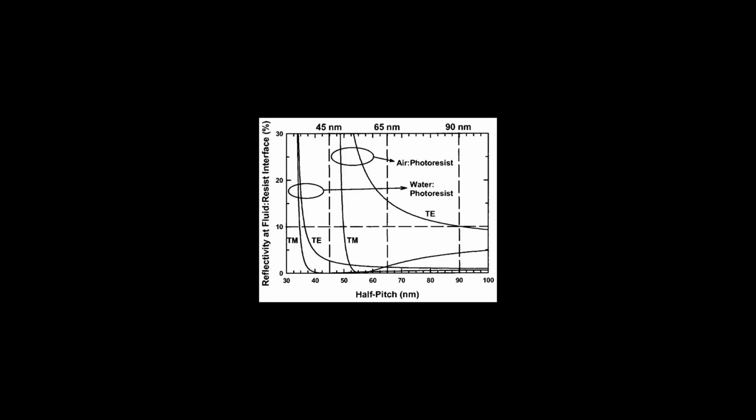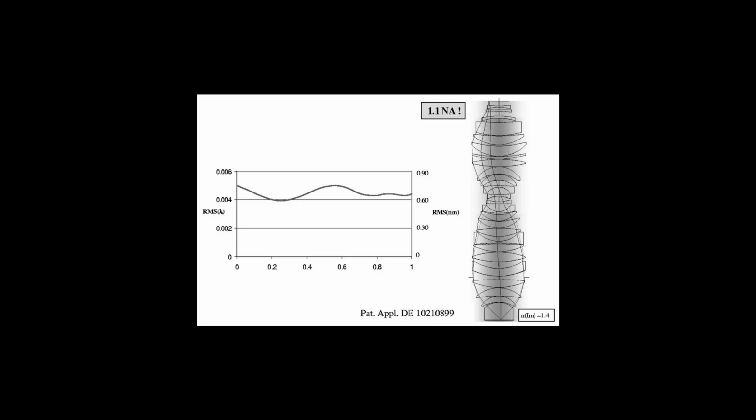However, it is expected that at some point below 40 nanometers, current photoresist will limit further scaling. Polarization effects due to high angles of interference in the photoresist also have to be considered as features approach 40 nm. Hence, new photoresists will need to be developed for sub-40 nanometer applications.